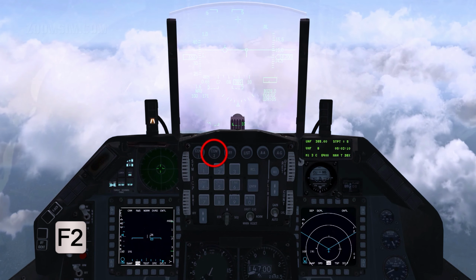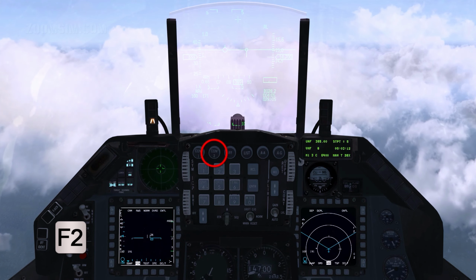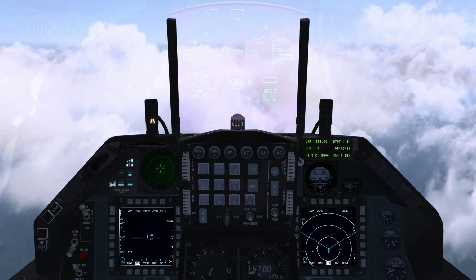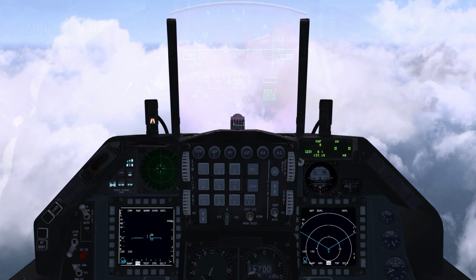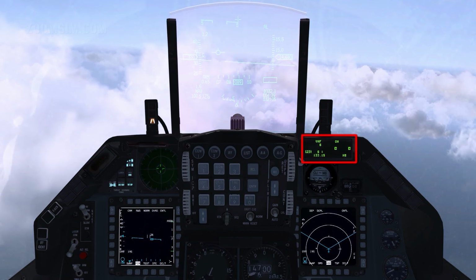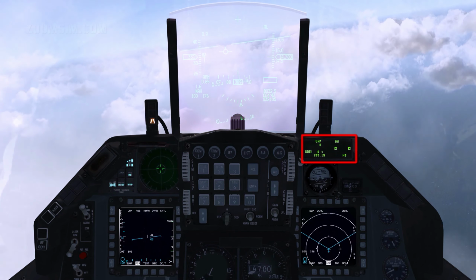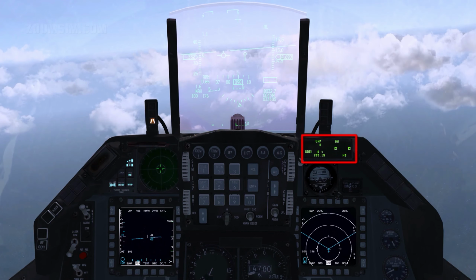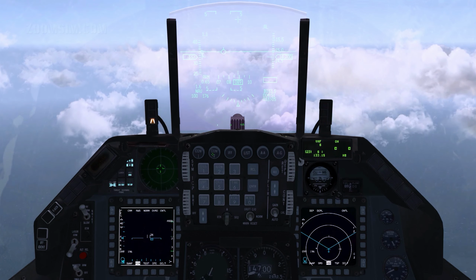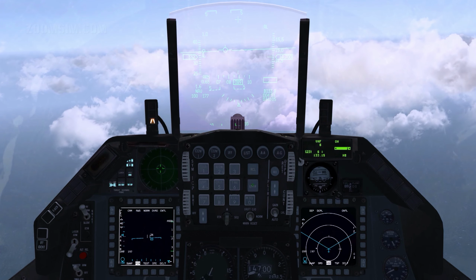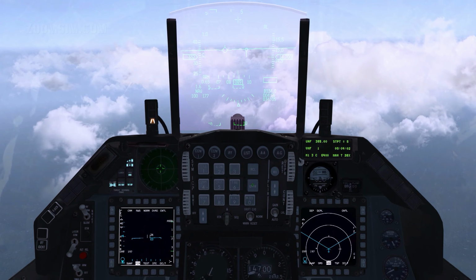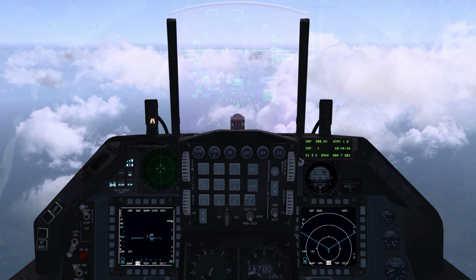To open the VHF or Victor radio page, press COM2. Victor is on and tuned to preset 6, which is set to 133.15. To change the frequency or to select a preset, use the scratch pad. The preset can also be changed with the previous next rocker switch.